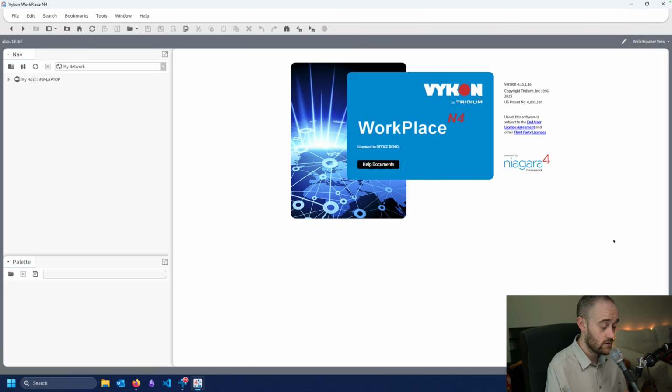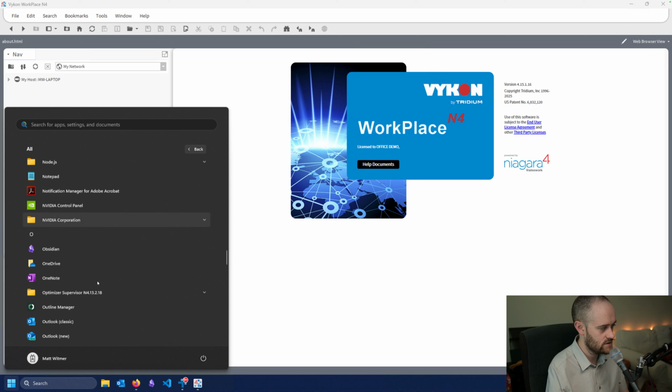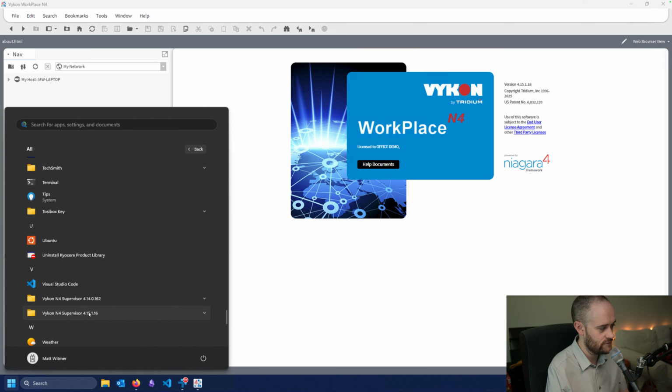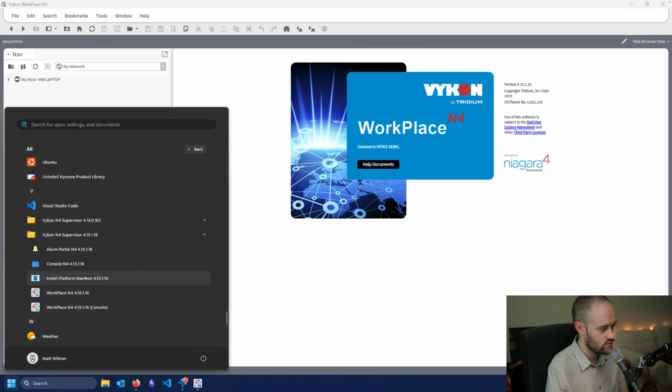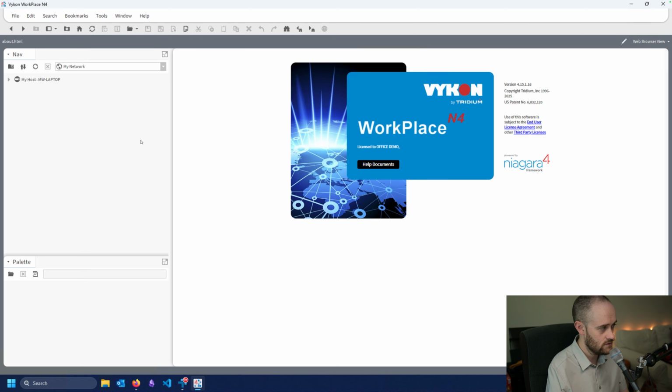All right, so we are in Niagara now, and first thing we're going to do is make sure you have Workbench open for the version that you want to use, and we're going to scroll down to that version, in my case 4.15.1, and then we're going to do an install platform daemon, and we're going to say yes. Give it a second, and then you should get a confirmation, and then the window should close. We're good to go. We have our platform running.